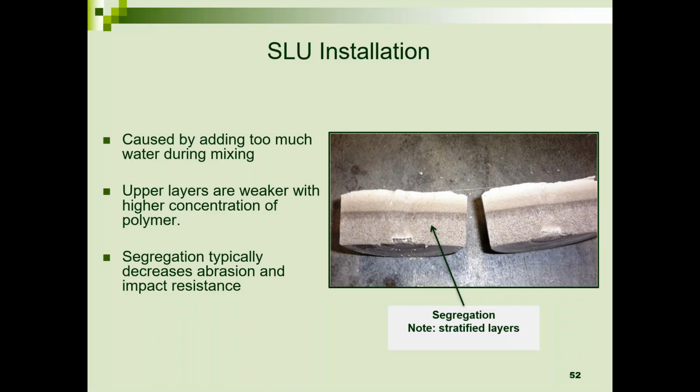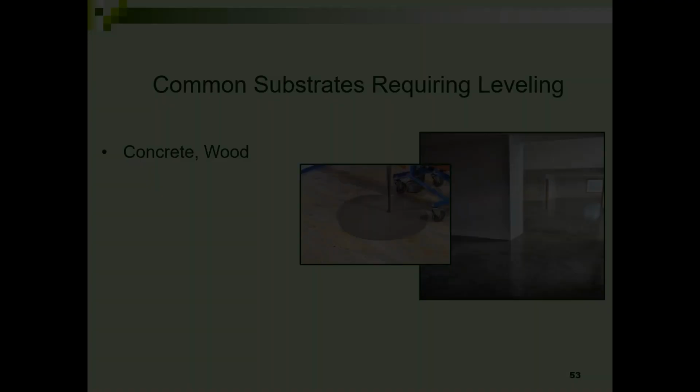And here we're looking at a self-leveling product that's been overwatered. What we see in the picture on the right is that all the heavy material, the sand, has sunk to the bottom, and all the lightweight material has floated to the surface, but there's no durability or strength in all that lightweight chemistry or compounds or materials that have floated to the surface. So the correct amount of water is very important. Too much, too little, the death of an underlayment product.